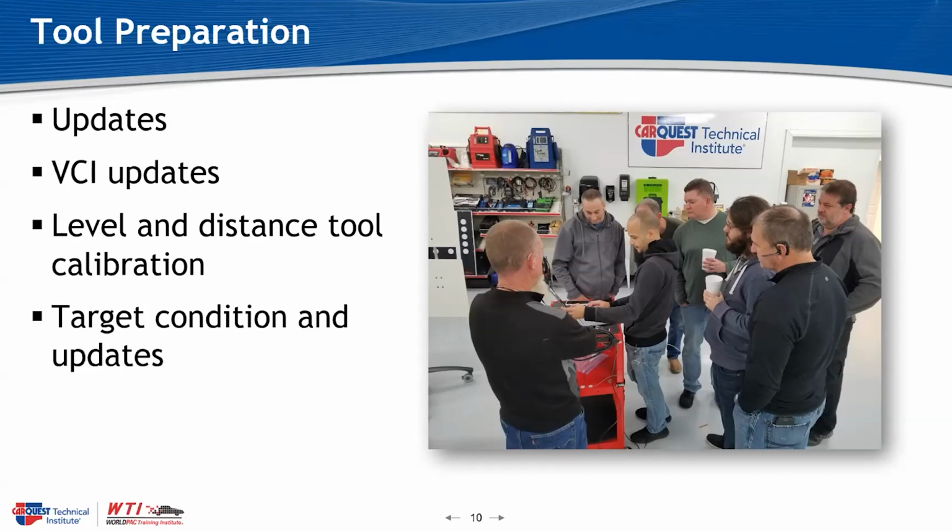So everybody leaves. I'm there by myself. I go back and think to myself, it's got to be something just simple. And sure enough, it was. Everybody had looked at the specs, and everybody had looked at the specs incorrectly, and the target was just not placed at the right height. Placed it at the right height, went right through, no problem. And that just demonstrates that in a lot of cases where you have a car that just refuses to calibrate, the problem is just very foundational once you dig through all the fluff.